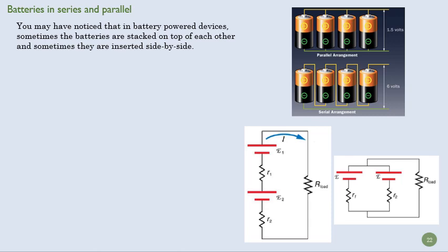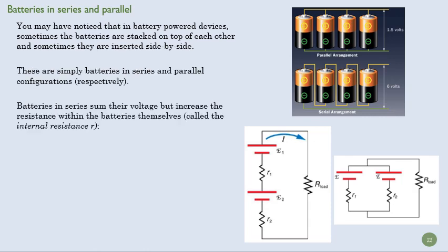Okay, so if I put this in series, let's say this is a 5-volt battery, right? This is going to be 0 volts. This is going to be 5. This is all going to be approximately 5. This is the internal resistance of the battery. And then this is going to bump it up from 5 to 10. So this would be about 10 volts. This would be about 0 volts. So they're working in similar kinds of ways, right? And they have different purposes, right?